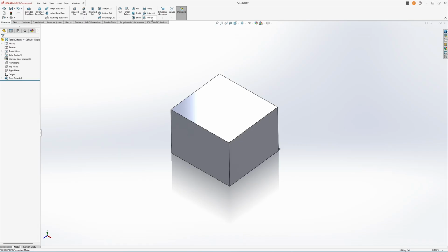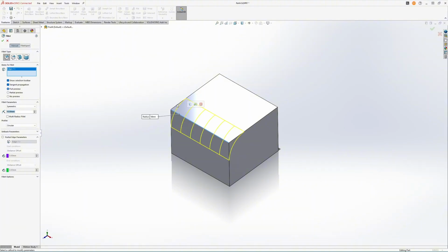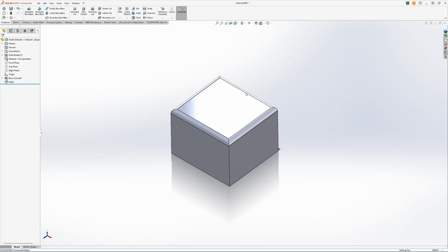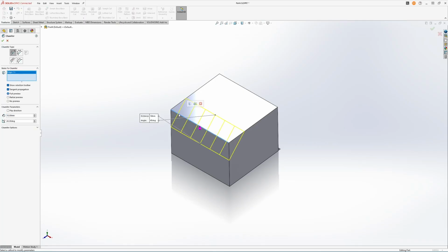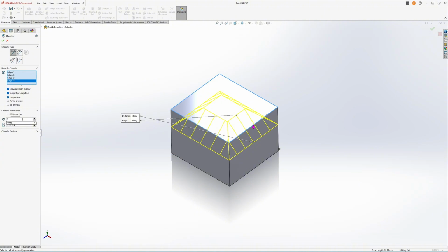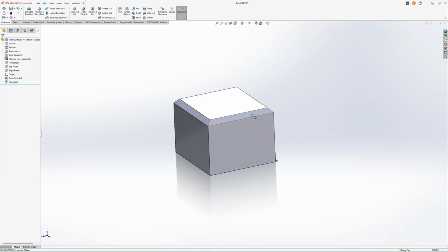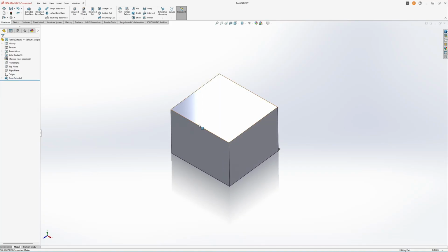Up here are like some different kind of modifiers. Fillets are very common. They basically just smooth off the edges of your part, like this. And we use them all the time basically to give it a nice non-sharp edge. We also have chamfers. If you click on the arrow there, and these are used a lot in CNC parts to break the surface. Or if you want to create something more interesting to look at, I use a lot of these chamfers just to make basic shapes. It kind of breaks the sharp edges.